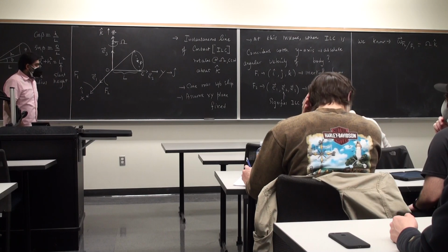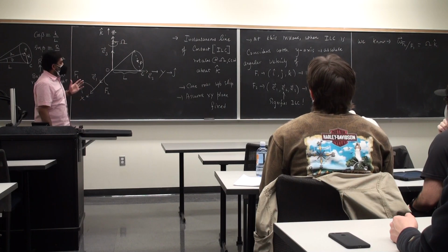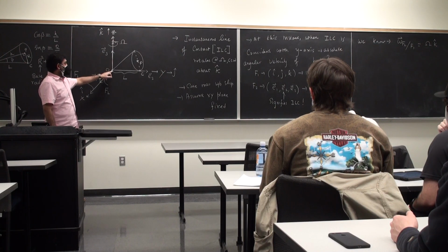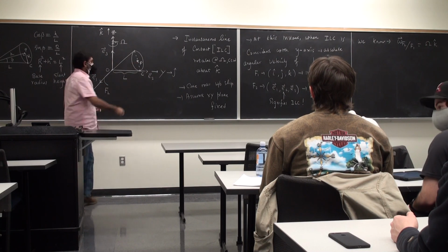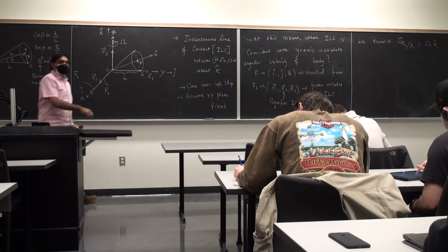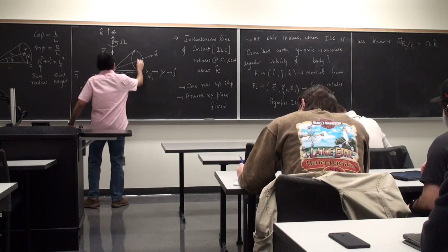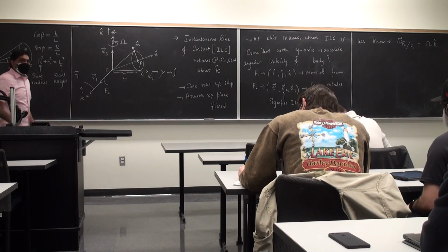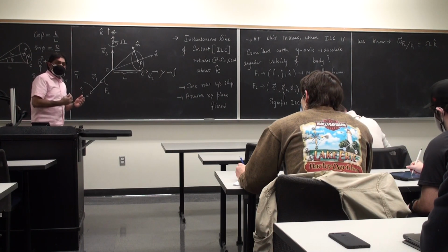We will make use of the symmetry of the body, and then we will draw a body frame. Okay? This body frame, I'm going to say, as one of the coordinate directions, is a line that is drawn from O to P. It pierces through the circle that you're seeing, the base circle. So that's one direction, at that instant in time. Then the other direction is parallel to the plane of the base circle. I'm going to call that M hat. And the cross product of these two gives me the second in-plane parallel unit vector, which is S.